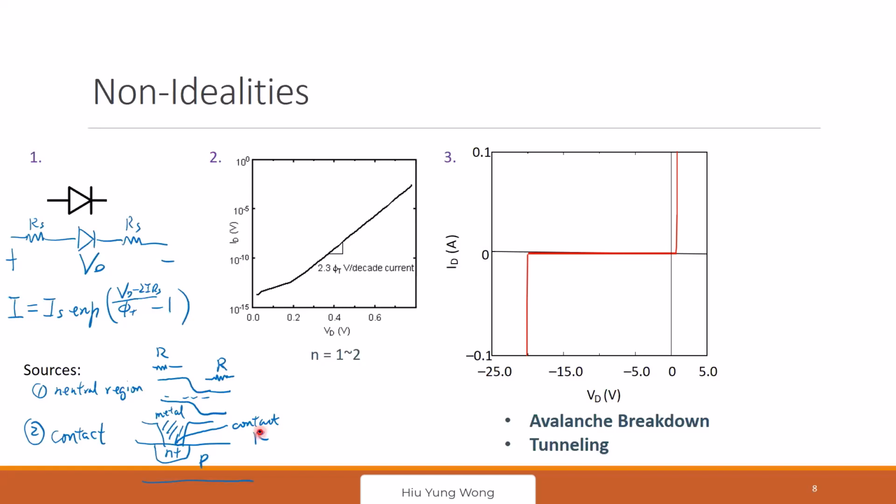So although here is only for diode, remember, this is also for transistor. And that's why we cannot just optimize the transistor. If I make a transistor really good, but you increase the contact resistance, no one is going to use this technology. So same for you as a circuit designer, you need to pick the right technology for your purpose. Okay, any questions?